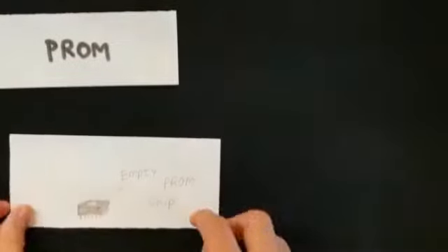Another type of ROM is programmable ROM. The user purchases PROM in an unprogrammed state. To write data into PROM, a special device known as a device programmer is used. It writes data one word at a time by applying an electrical charge to the input pins of the chip. Hence, users cannot change the content after programming it. To change the content, the user needs to discard it and rewrite on a new PROM. Thus, this makes PROM also known as a one-time programmable device.